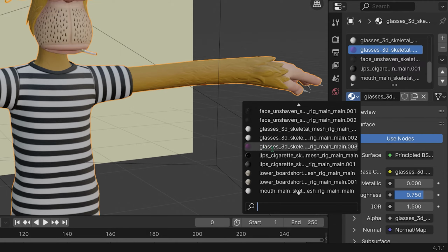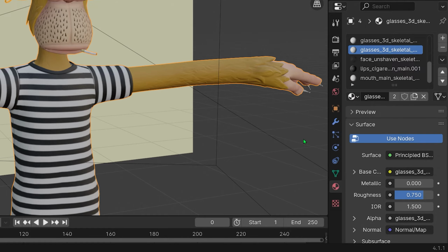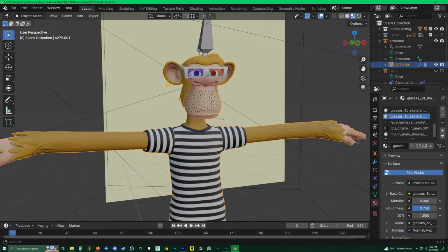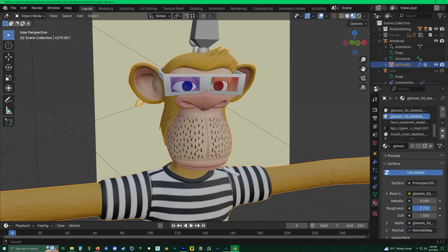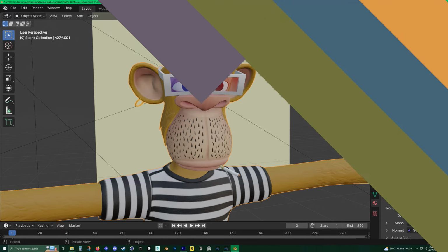The small spherical color previews to the left of the texture showed one was pink and the other was white. Not sure how this happened, but I selected the other file to replace it and it seemed to fix the issue. If you have any issues with your materials after exporting, you could try switching out the textures accordingly if you see some duplicates in that list. Just make sure to save a copy of your Blender file if you haven't already so you don't overwrite your